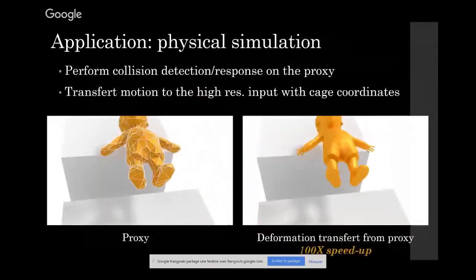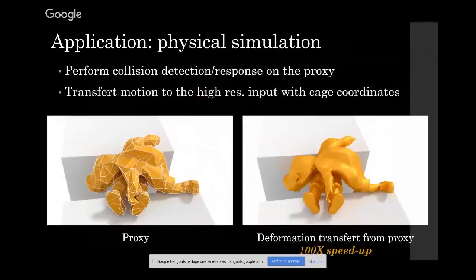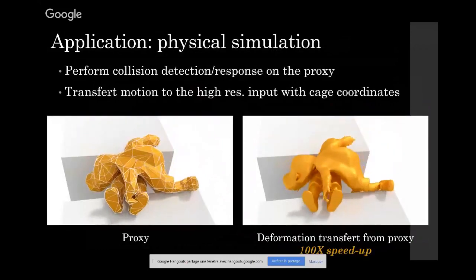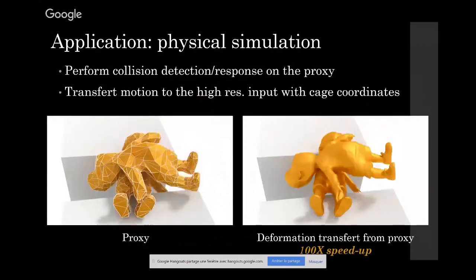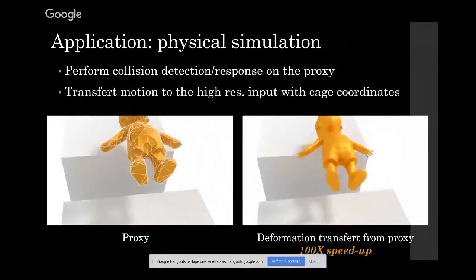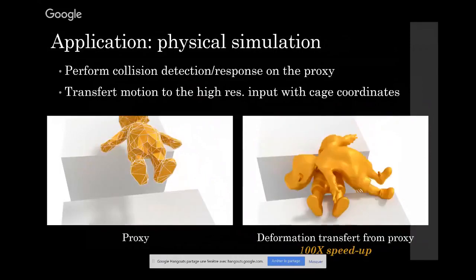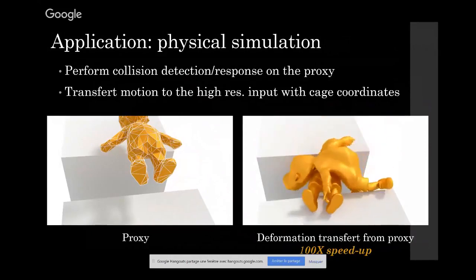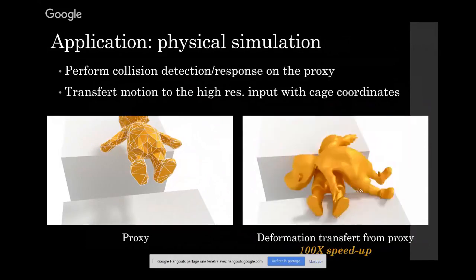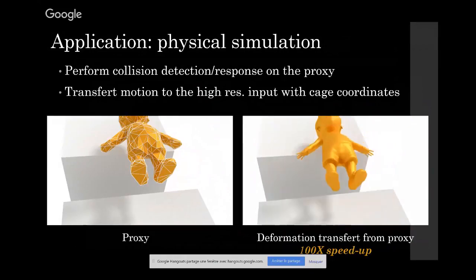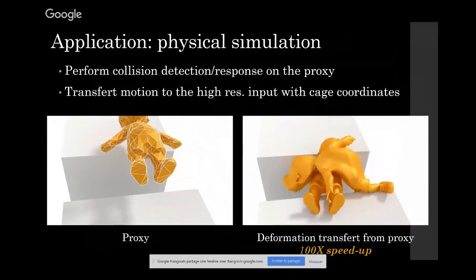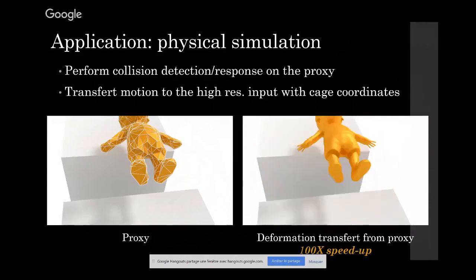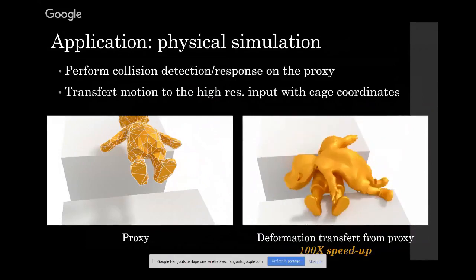Now, what you just saw was actually a volumetrization that was rendered in real time. We don't extract the final mesh in real time. It's more like a final baking stage here to extract the mesh. But this has an interesting application, not only in interactive editing, but also in physics simulation. You see here those deformable bodies, which are computed with the proxy for the physics, but keeping the high resolution model for the rendering. And when you do that, of course, you really want to be conservative, because you don't want your pieces of geometry to cross each other.